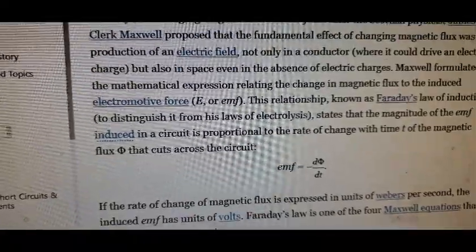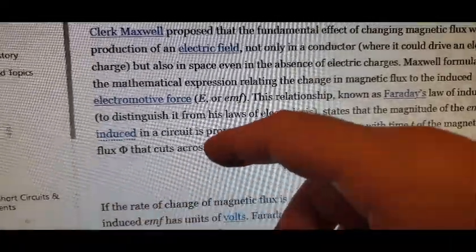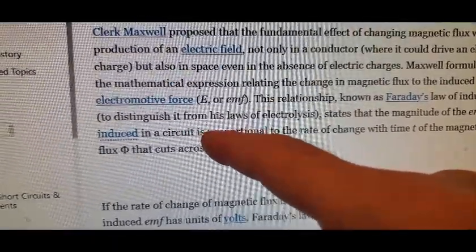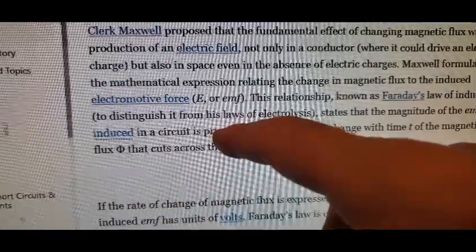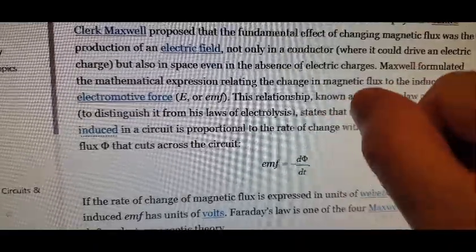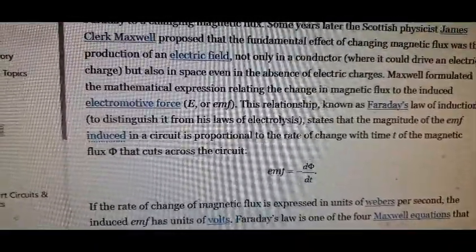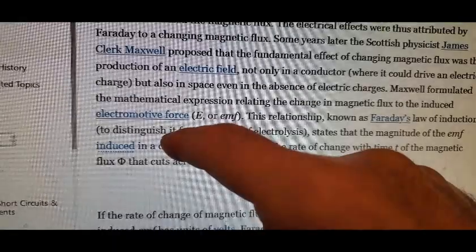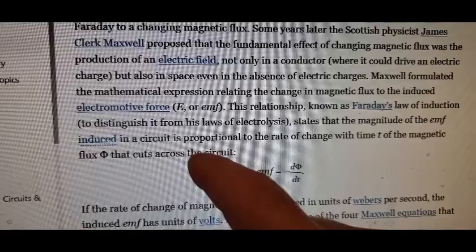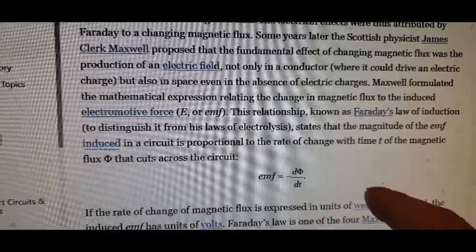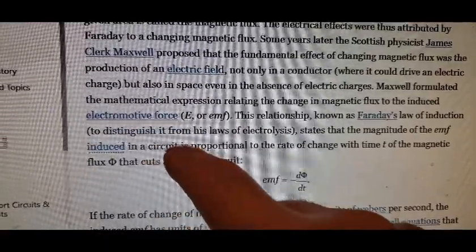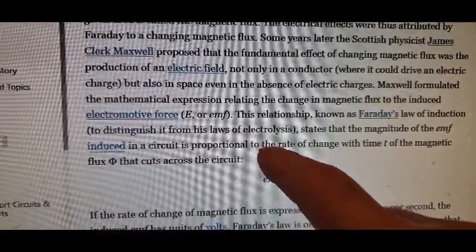So let's again say it's a coil that at 10 volts, once it's reached its steady state and is saturated, is drawing 1 amp. So you would put the current in and it's drawing 1 amp for 10 minutes, and then you shut it off and you get a spike. But you could also put it in for 1 minute and then shut it off and you would get a spike. And so if you're trying to gather energy off the spikes, the second approach would be 10 times as good, because you didn't just leave the coil sitting there with no change.